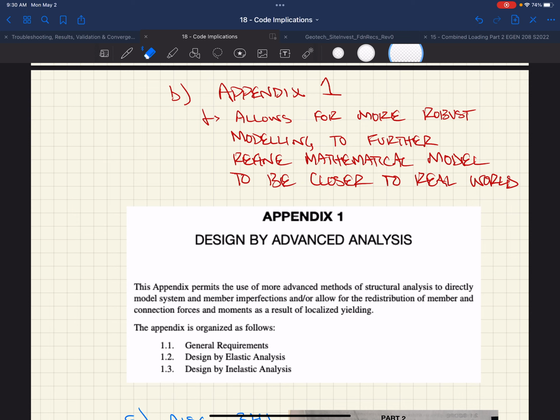These connections, right? Like that it's within that elastic region. Well, yeah, I mean, deformation, I would imagine. Yes, I would say that they're more worried about relative stiffness being the important part about these connections, right? And that's why with partially restrained moment connections, you have this torsional spring, right? So it's like, where does your connection land? Is it going to be completely fixed and not allow much rotation, right?